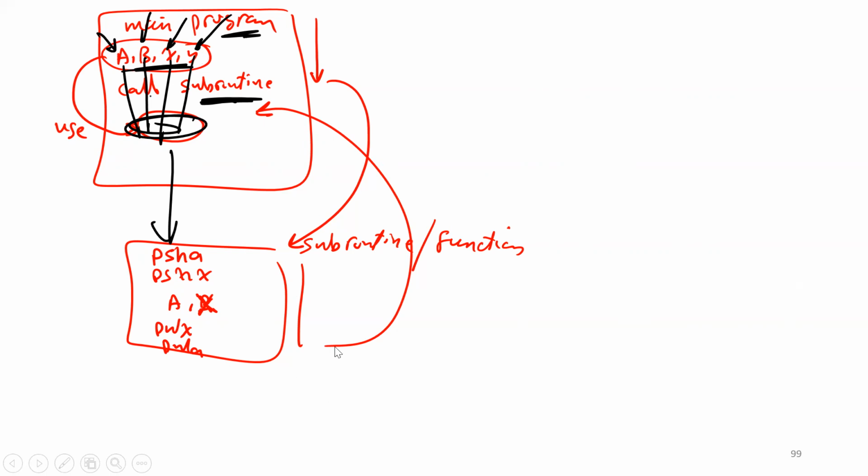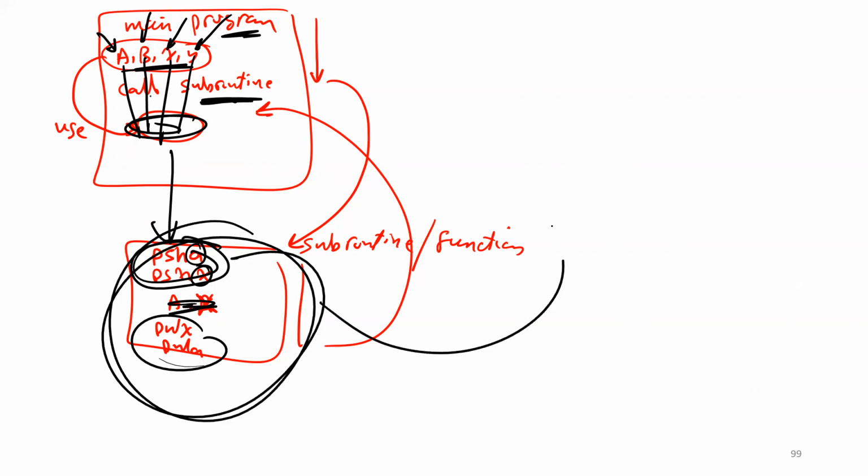That is why you will see in the next section, which is the last section about subroutines, that all the time in subroutines we do something like this. In this subroutine, I'm going to use register A and register X, so I'm going to push A and X, and then pull X and A at the end, so that the subroutine does not interfere with the main program. Inside the subroutine, I can still use the registers without causing problems for the main program. You got what I'm saying? So all the time we will do that.